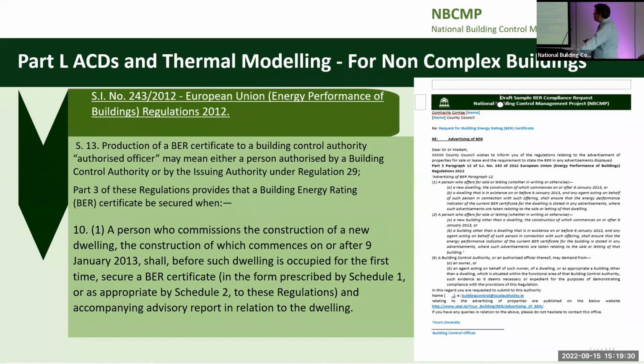So a person who commissions the construction of a new dwelling, the construction of which commences on or after the 9th of January 2013, shall, before such dwelling is occupied for the first time, secure a BER certificate in the form prescribed and an advisory report. And that's a regulation that's required. And the enforcement authority for this is the building control authorities. And SI 9 is also enforced by the building control authorities.